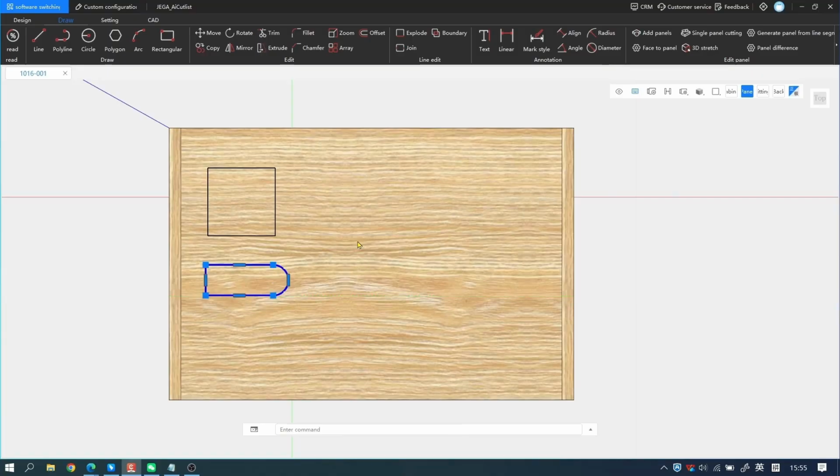Next, you can use this command to create a continuous line. And you can see its shortcut key is PL. So you just input PL and hit the space key. Now you can simply left click to pick up the first point and move to the right side. Specify the dimension, press the space key. Now you can move to the top part, input the dimension and press the tab key to save this value and move to the second field and input the degree of this line, 45, and space key again.